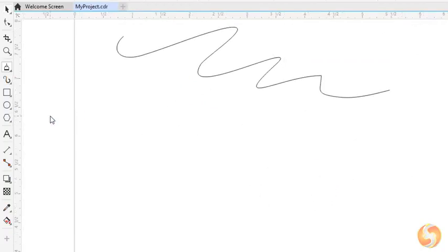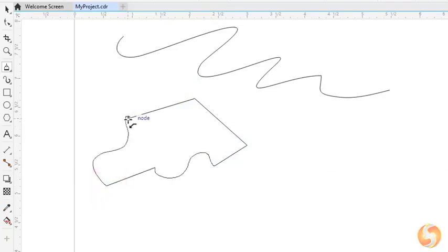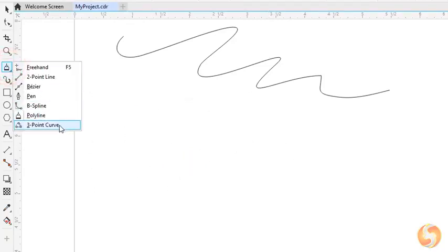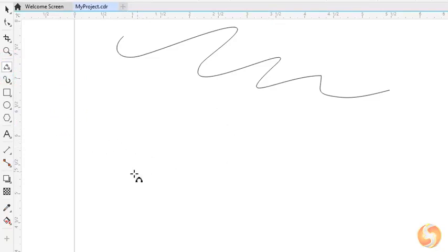With the Polyline tool, click several times to drop straight segments and click and hold to draw freehand as you like. Segments and curves follow one after another until you double-click or close the shape. Use the three-point curve to drop arcs by clicking and dragging to define the basic segment, and then release and click to define the arc.